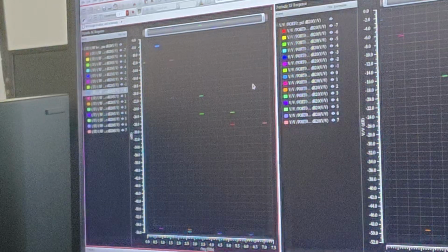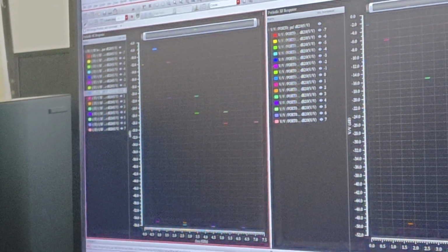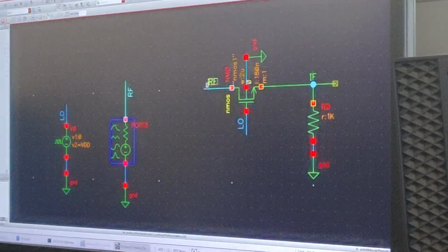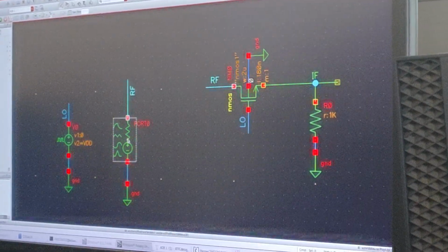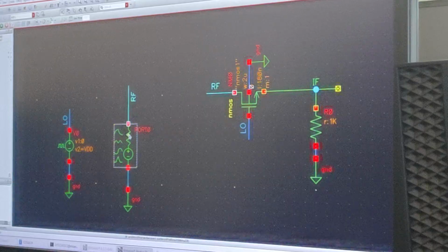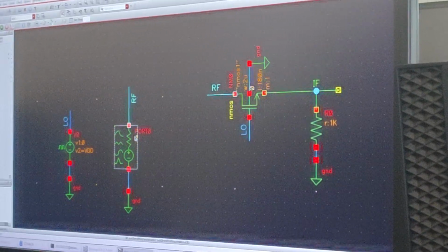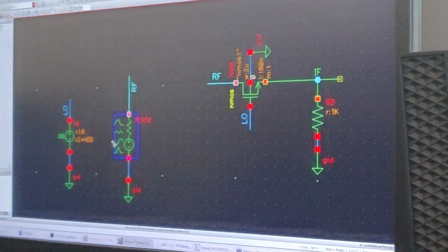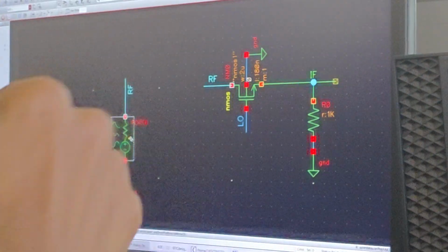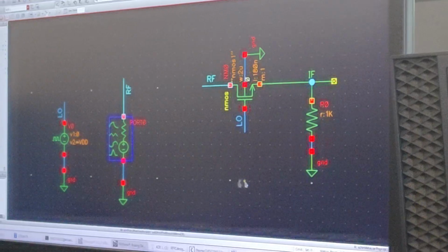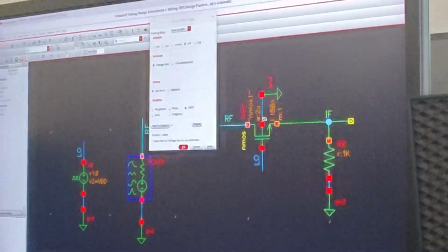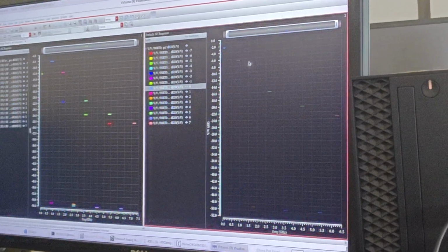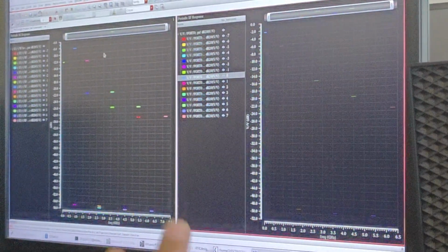When you are doing PAC analysis, you are specifically taking this as the output and this as the input. But when you are taking the port of the circuit, it is like the first experiment earlier. When you were practicing, you got that 6 dB difference because your voltage source and resistor are there. But here you are selecting the port, and based on what it is giving inside, it will check. So if you want to see what comes with respect to the output axis, you can see this one.